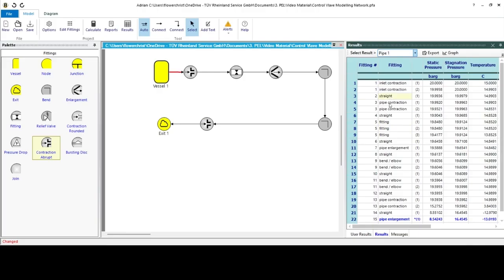And as we look through our model now, again, this is our control valve here. Actually, what we're seeing is that we haven't got choked flow at that point. The choke is actually coming right at this little end here, the end point. So mimicking this as an orifice isn't really that reliable because it's not behaving in that kind of way. What it really is behaving as is just a fitting like any other fitting.